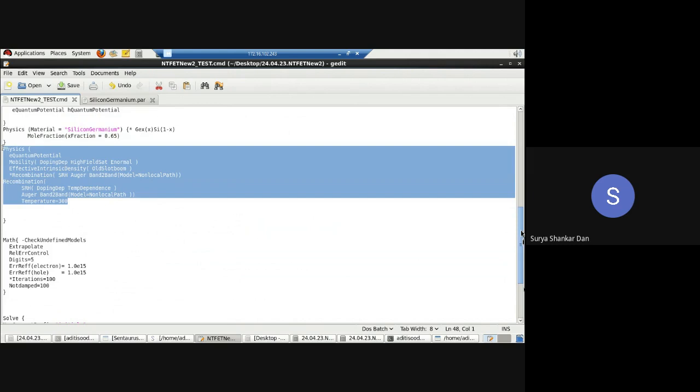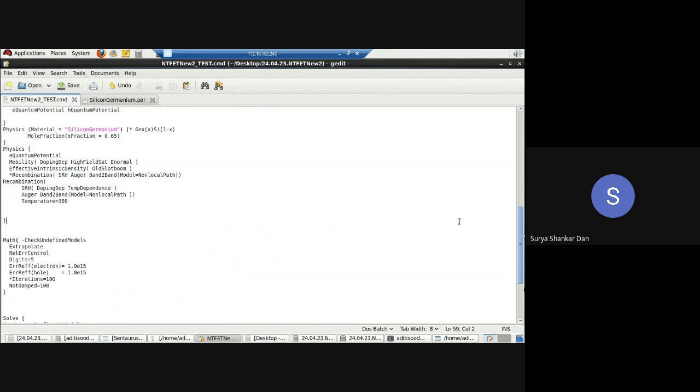For example, we are working on memristors. These memristors do not have a model. In the future, when somebody comes up with a model, it will be incorporated as one of these header files which you are seeing over here. Somebody 20-30 years ago came up with this band to band application model which is incorporated in Synopsys. Remember, not the mathematical model. The mathematical model was developed by Kane in the 1960s with the tunnel diodes. Don't confuse the two. How Synopsys incorporates those mathematical models is the question here. That is coded in C++ and put in over here. So that is what Aditi is using right now, the band to band.